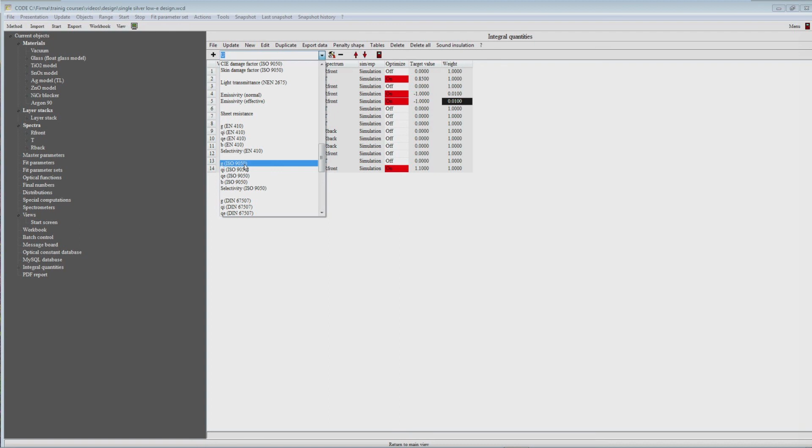Let's say in the front pane there's an absorption, in the coating and the second pane there's absorption. So the glass panes heat up, and so they start to radiate and they start to emit energy to the exterior and to the interior of the building. And these flows of energy are called QI and QE. And if you add the QI value to the solar transmittance, you get the G value.